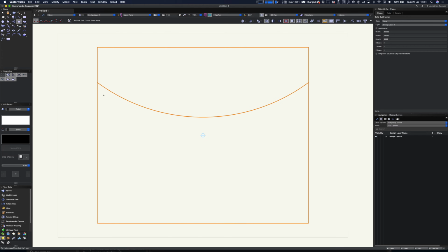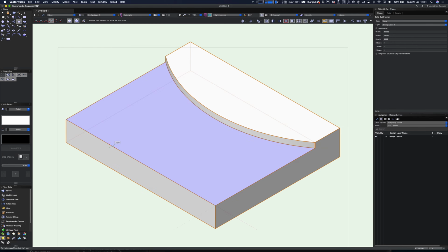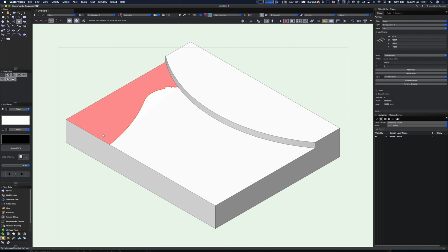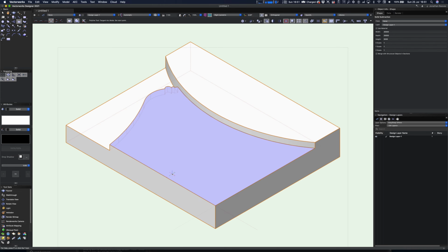So what we'll do now, we'll pop it into 3D view and we'll basically get our polyline tool. Make sure you're using the fourth mode of this tool, and basically we're going to draw again on the surface of the model. Just make sure that you're using the automatic plane, just seeing if I can find those snaps. Doesn't really matter because we're just going to eyeball this in, double click, and I should find, if I do this right, I can snap to that surface. I think I might have just missed it. There we go. And just pull that down. Made a little glitch at the end, but we can sort that out easily. So I'm just bringing that down by, say, 1 meter.